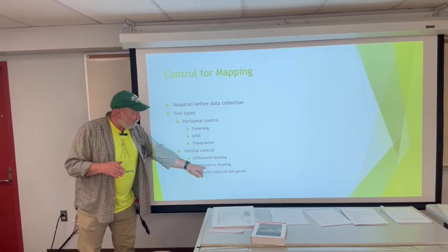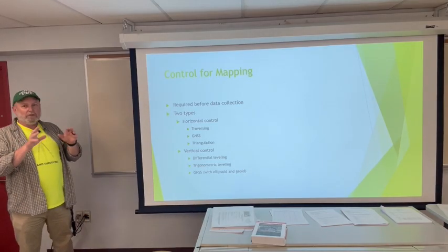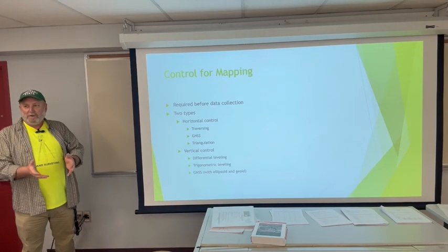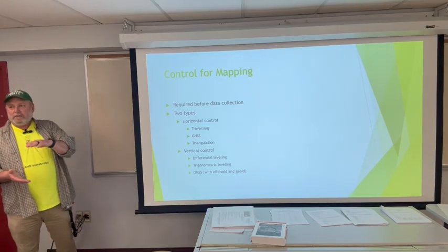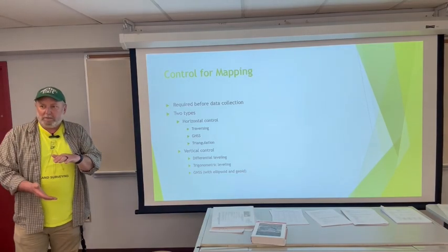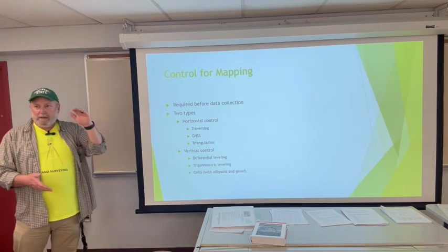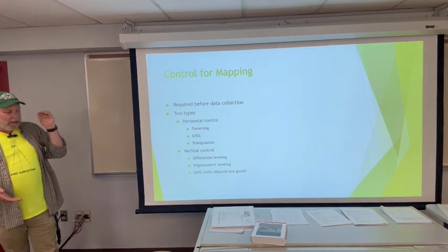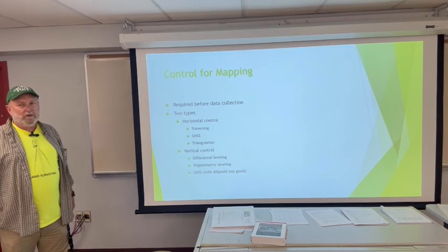From the ellipsoid height and the lat-long, the software knows where the geoid is in reference to where we're standing, and measures the distance from the geoid to the ellipsoid. When we do the math of the ellipsoidal height and the geoid height, that gives us an orthometric height, which is also what we refer to and call elevation.